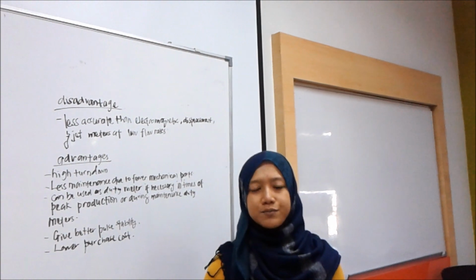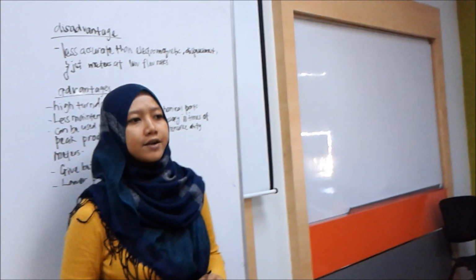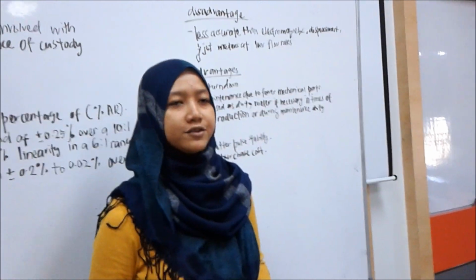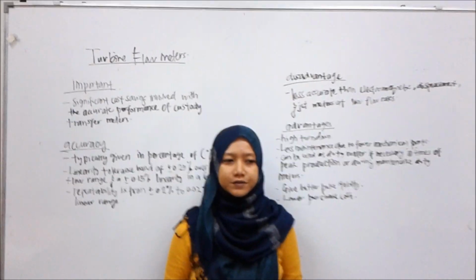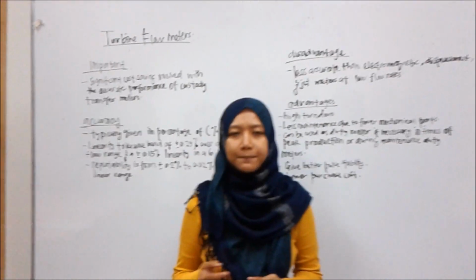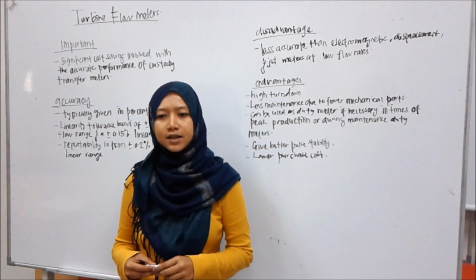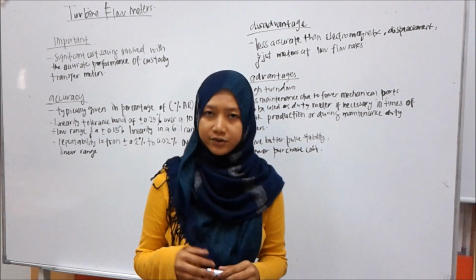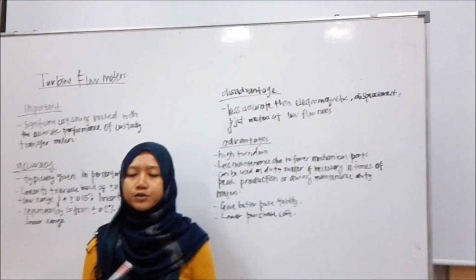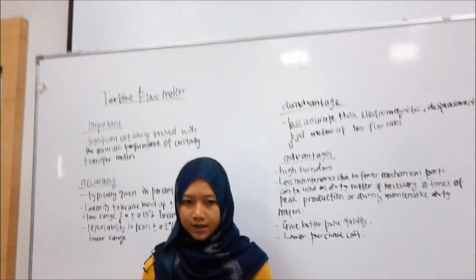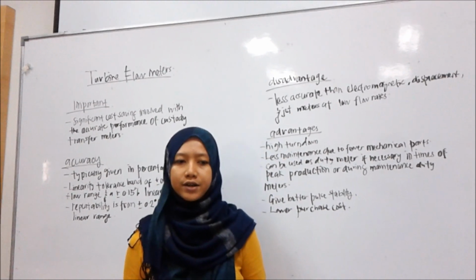And of course, the most important is lower cost. As mentioned above, there's a significant advantage by using these as the master meter. So I think the best selection is this turbine, the most reasonable and best solution, especially to be used in our field labs. When using a turbine flow meter in these labs, the unit reduces the overall size requirement, reduces overall maintenance of the metering skid, and provides an easy way for users to verify metering skid accuracy.